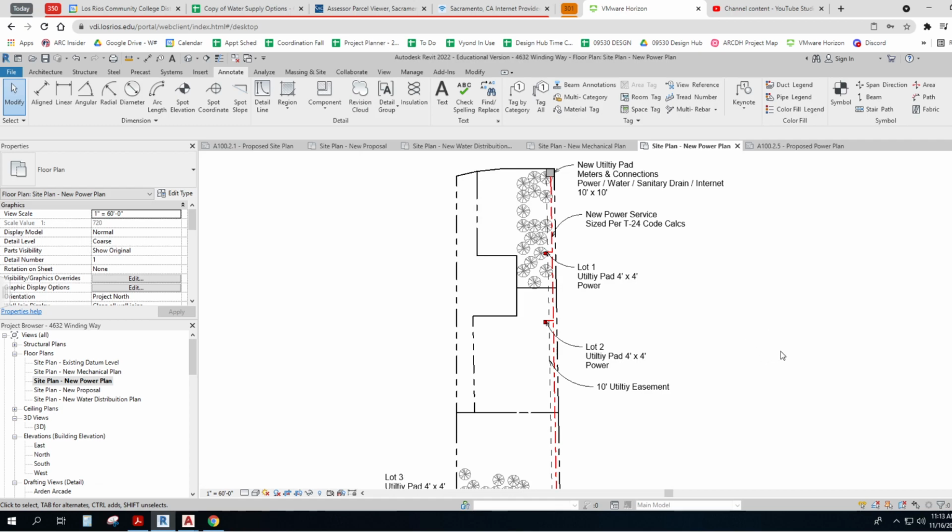So the main one being, as you drive over things, if it's not well compacted, you actually put stress on the items that are down there. So an electric cable doesn't really matter that much. It can bend a little bit, but your water lines and your gas lines and your sanitary drain lines and your internet lines don't like to be underneath roads near the surface.